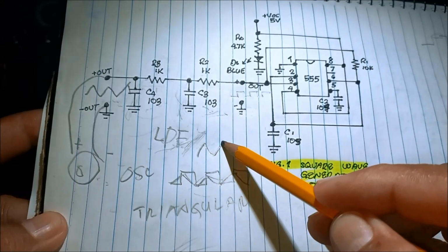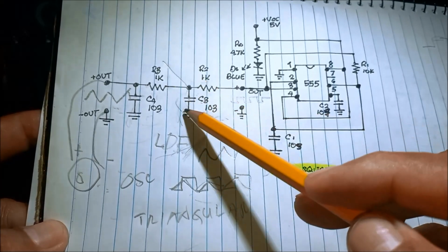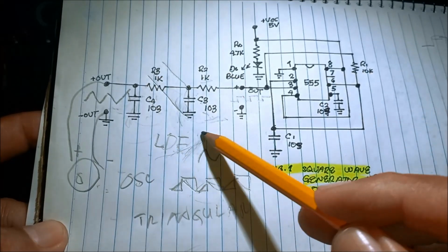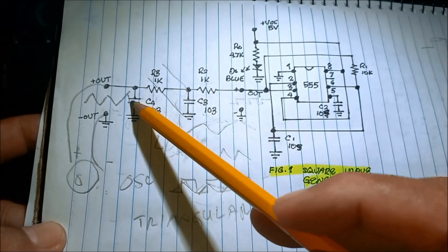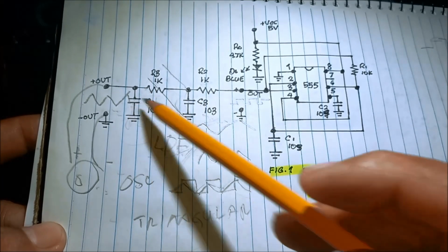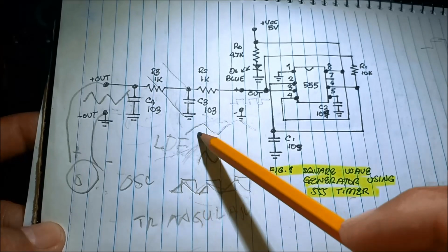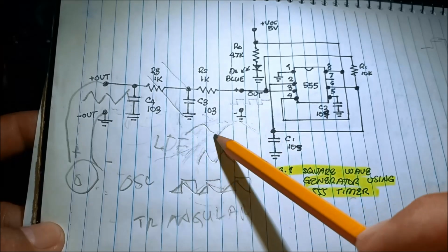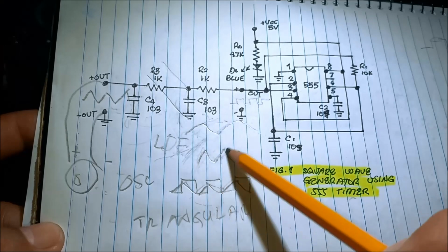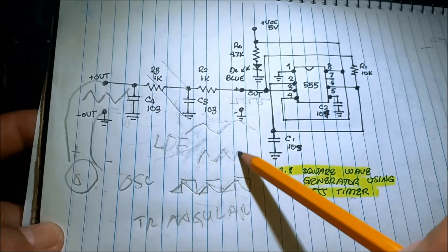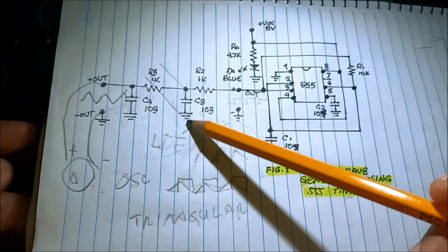a nice triangular waveform? Because in the first set, if we connect the oscilloscope here, the charging is wider. Looks like this. Again, with the use of another set of filter, it will make this type of waveform now. Instead of a wide form of triangular waveform, a steep, slant looking waveform is now being created with the use of two sets of low-pass filter.